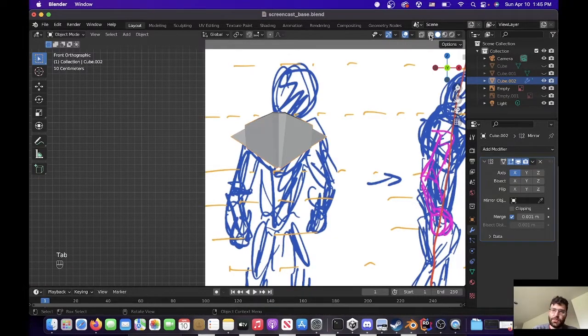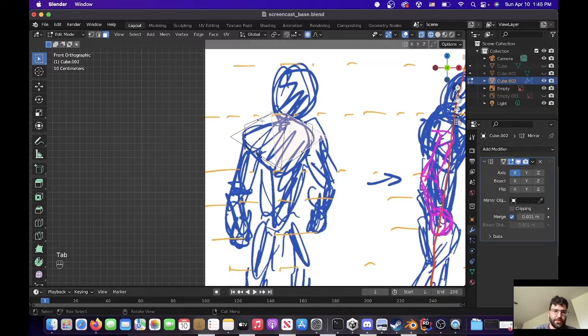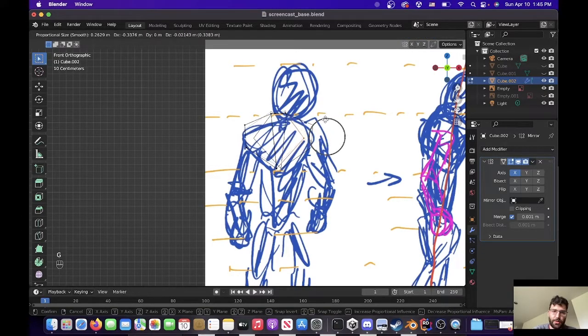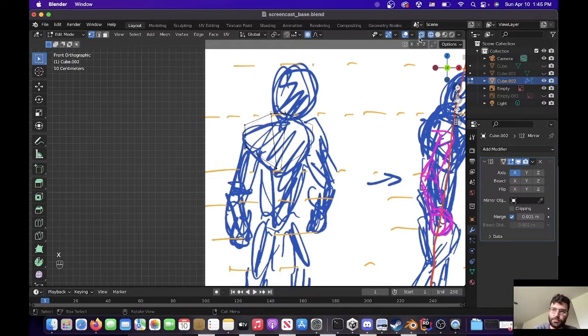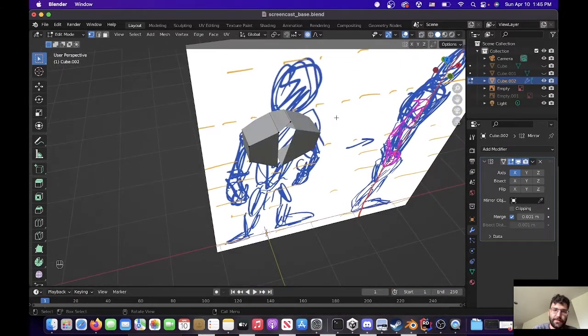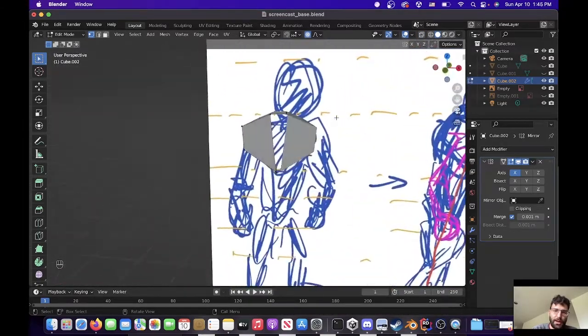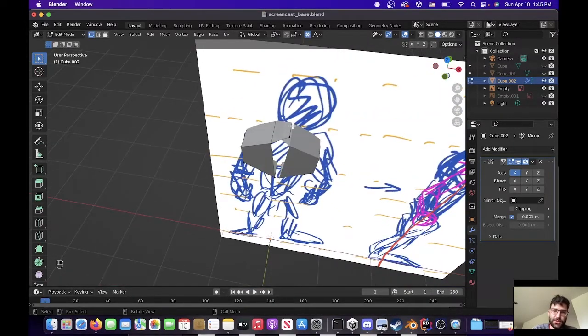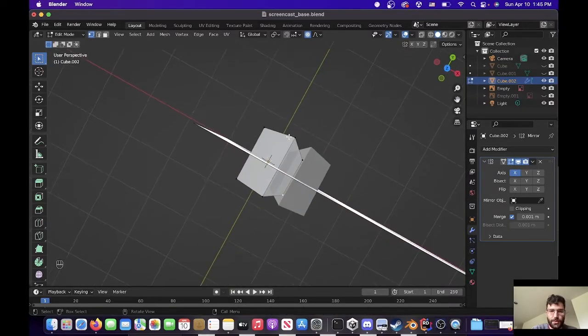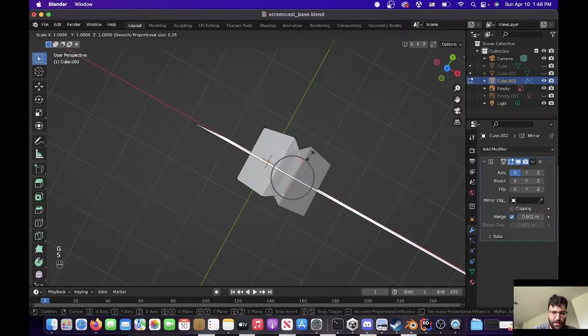Going into edit mode and wireframe mode, you can see the source of the problem, which is this point over here is kind of making a mess for us. So we can literally just delete that point. Now we have a new problem. There's a big hole in our mesh. That's also solvable. So you take these 2 points over here and you scale them out like that.